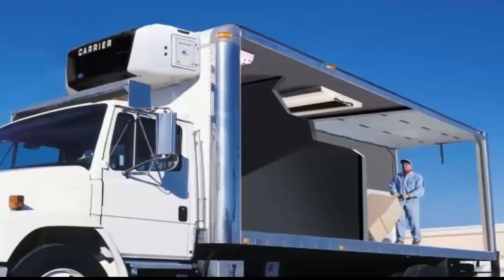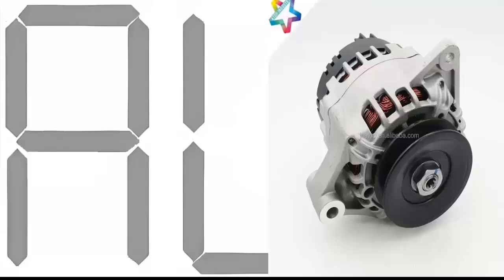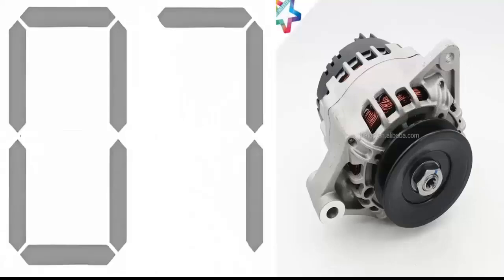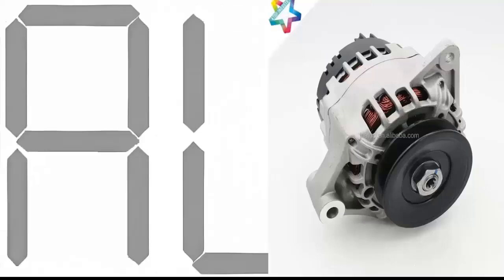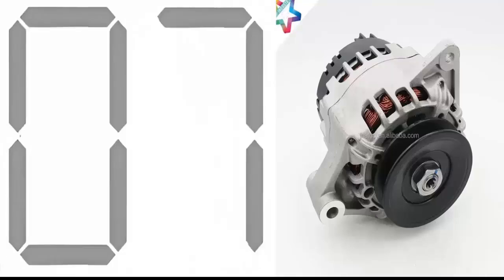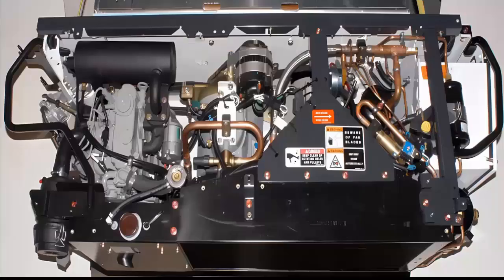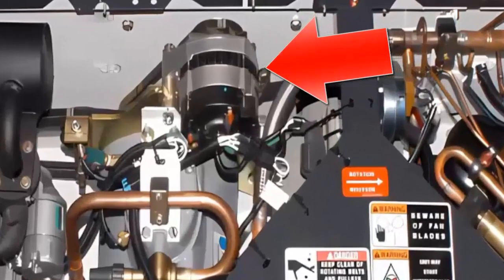8. Alternator failure. Identified with code AL7, this fault occurs when the alternator does not provide the expected signal while the engine is running or in standby power mode. It is recommended to check the alternator and its connections.